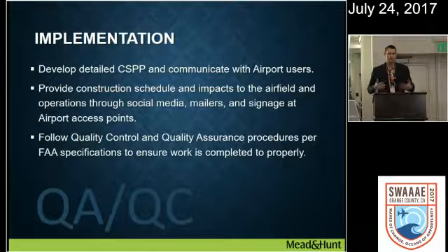projects, is that when you do the marking removal, drum grinders work extremely well on non-grooved surfaces. Water blasting is also an option. But when you get on the grooved runway surfaces and you have to relocate markings, it is a very big challenge to be able to remove that marking effectively and not have that shadowing or ghost markings after, without having to replace the asphalt, which the water blasting really does a detriment to those grooves.